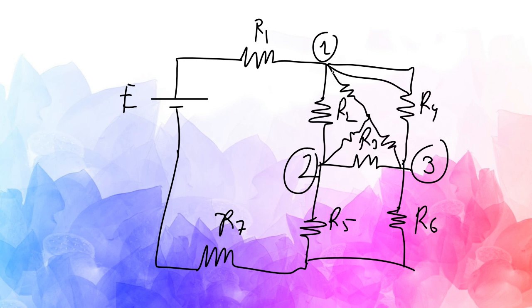Now just see this resistance, after that these are in series. So this has become a simple series parallel circuit. Now this is in series, so we can go with simple addition. Then R2 and R5 will be added, and R3 and R6 will be added. After that, we just need to draw a parallel circuit.